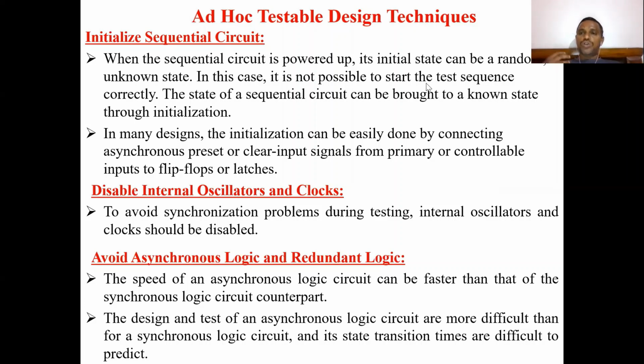If you don't know the state of the sequential circuit, it is not possible to apply the test sequences. So to avoid that, we initialize the sequential circuit to a known state. The state of a sequential circuit can be brought to a known state through initialization.